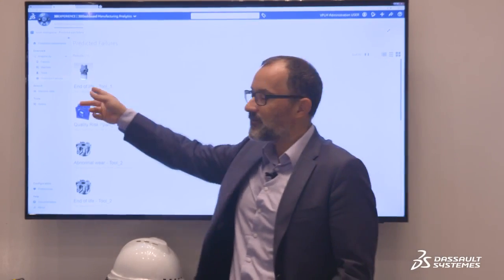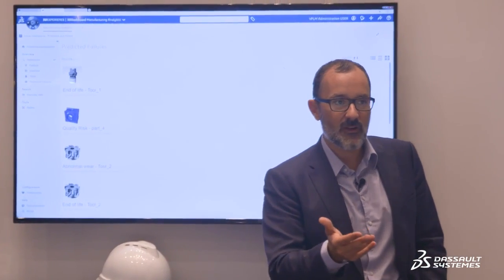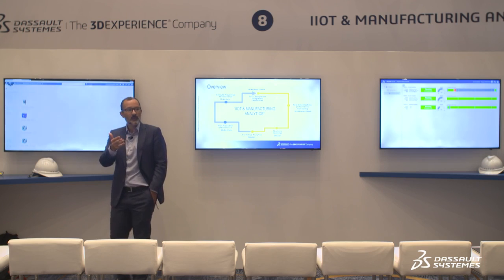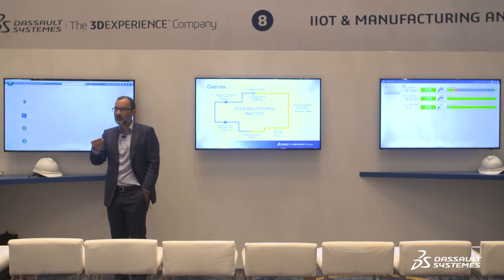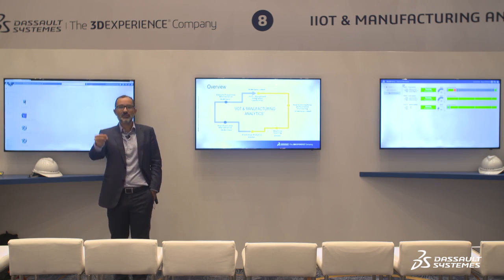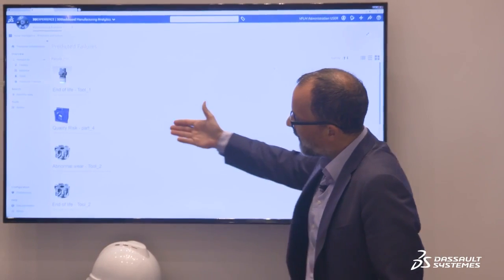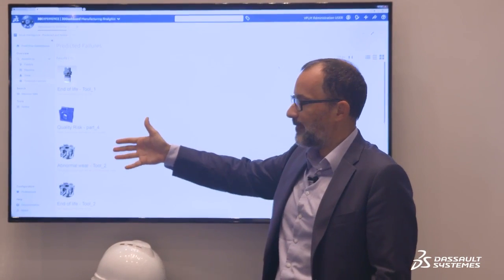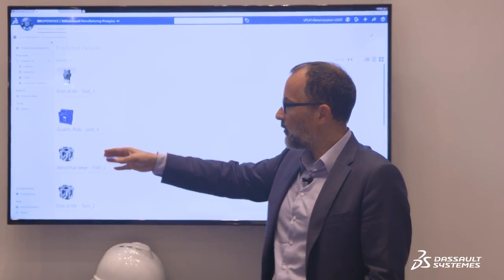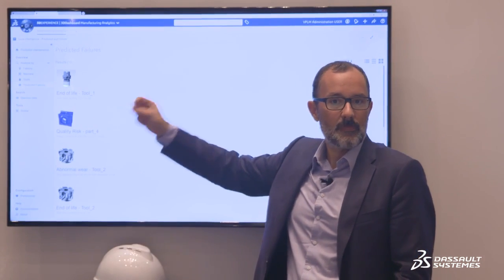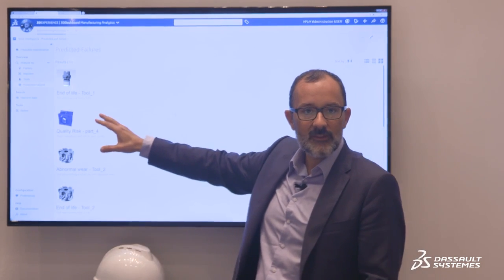However, the end of life of a tool is a normal failure that we could have planned. But the fact that we could have planned it doesn't mean we decided not to still use technology and algorithms to optimize the best potential date for changing that tool. And of course, we have abnormal failures, such as abnormal wear on toolings or quality problems. We will come back to these issues later.